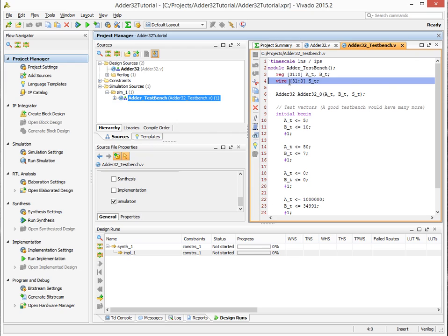And then the wires are going to be used to connect to the outputs of the adder design, because we're not assigning anything to the outputs, we're just observing what those are, so we're going to connect that to a signal. In our practice here, we have an _t for each of the signals. That's to help us differentiate the reg variables and the wires used in the test bench itself compared to the internal ports of the adder design.